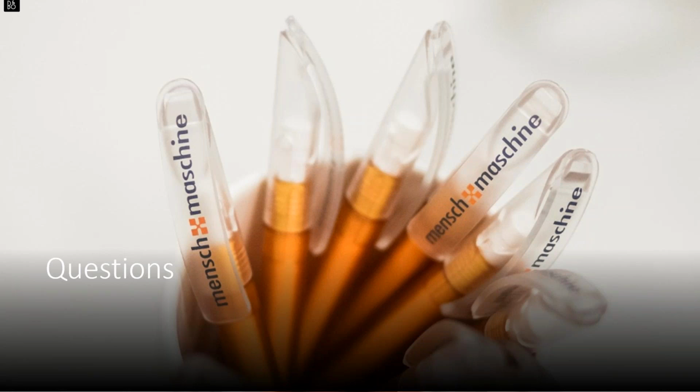Your other option, of course, especially if it's in AutoCAD, is to use the factory material flow analysis. So you can take your 2D layouts, it doesn't have to be factory assets, and block them to different zones or different bays. Once you've made those blocks, you can assign them as your various areas within your factory layout, and then you can assign a material flow analysis through the AutoCAD side of your factory utility tools.